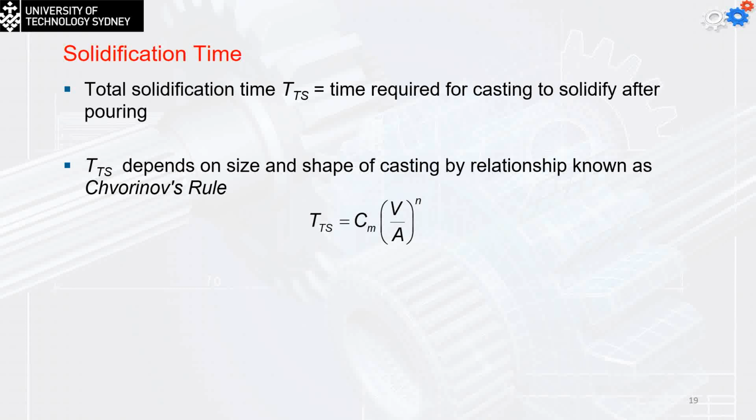For example, if I solidify 1 cubic meter of molten metal, and it's 1 by 1 by 1 for the volume, it's going to be compact. The surface area exposed to the air is going to be 5 square meters, because the other side is on the base. While if I do the same thing but make it a flat plate, I will increase the surface area, so the cooling rate is going to be higher.